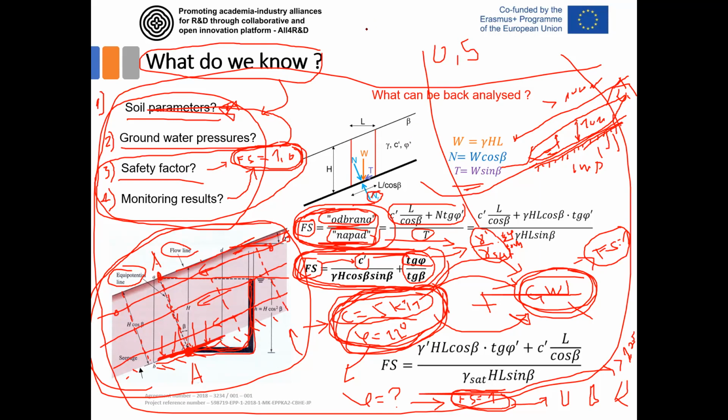That means if you had a safety factor without water equal to 2.0, after the water, that means the submerged safety factor, will be 1.0. So you were quite safe from failure before the water reaches the slope, and after the water you have a value at the verge of failure.